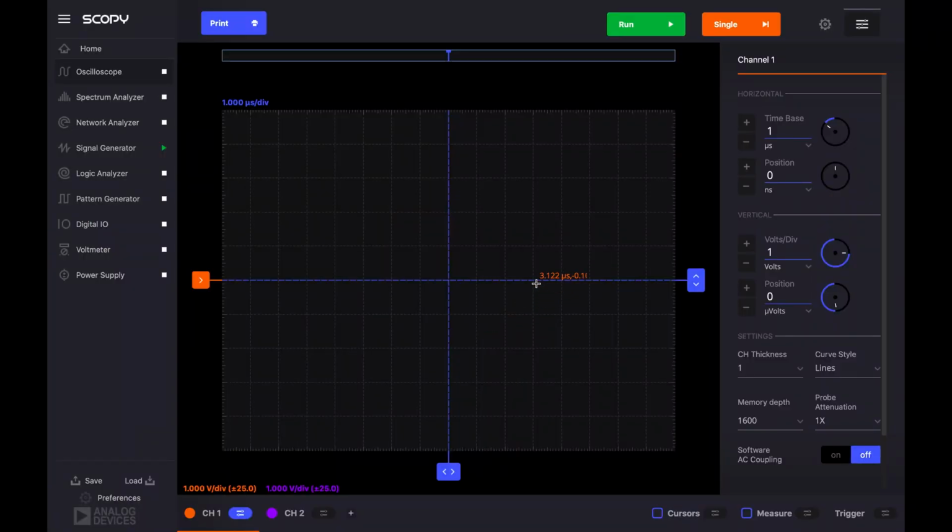We want to measure the time constant of this RC circuit. Great. So here's what we do. I open this up, and this is a brand new configuration. I have not changed anything. Right off the bat, you should also see that my scaling's a little off, but if you look at it, you actually get a reading on your cursor when you move it around. So right now it's minus 2.2 microseconds and 3.3 something volts maybe. This is very useful to be able to look at specific points in your graph.